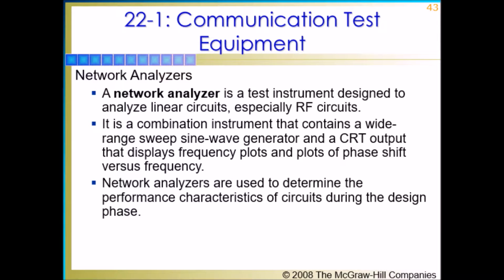Network analyzer. It is a test instrument designed to analyze linear circuits, especially RF circuits. It is a combination instrument that contains a wide-range sweep sine wave generator and a CRT output that displays not only frequency plots, as does a spectrum analyzer, but also plots phase shift versus frequency.